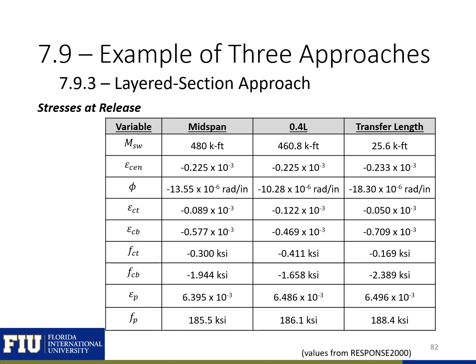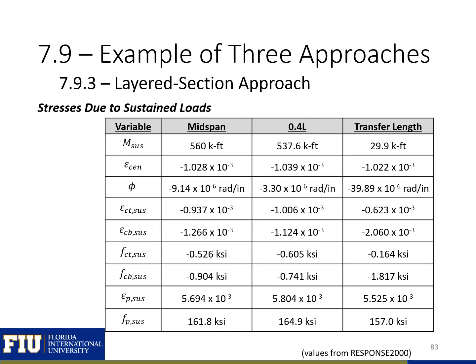As we saw in Module 5, Response 2000 is a freely available layered section analysis software. And using that, we can find our stresses at release, which are summarized in this table for our midspan, 0.4L, and transfer length locations. Shown on this slide is a summary of the stresses due to our sustained loads using our layered section approach.